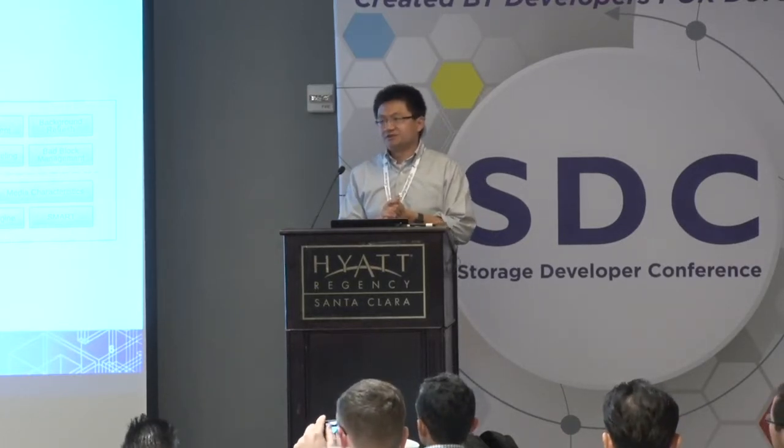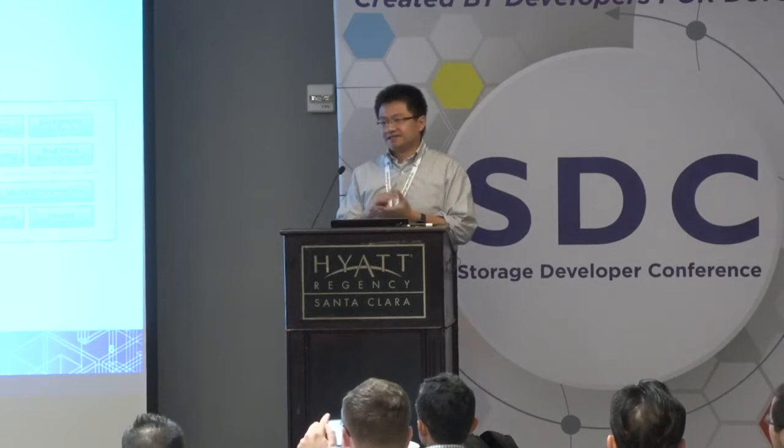You mean I/O determinism? Yeah. So I think this way is also for the good of I/O determinism. For the traditional SSD, it will do those work for you, right? Without your permission. If the traditional SSD finds the data there has some retention issue, it will just move the data, and the host side has nothing to do with it and doesn't have any control there.